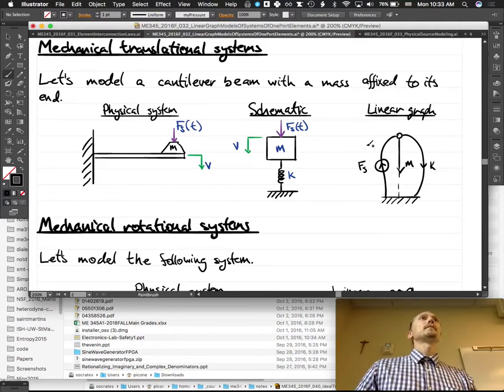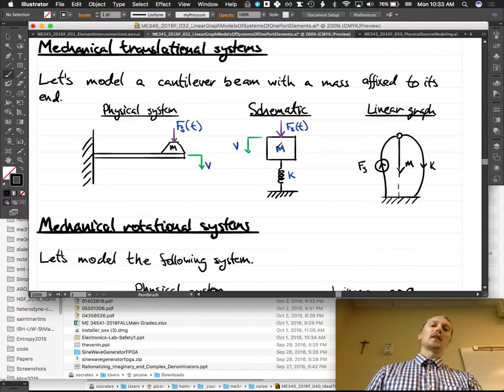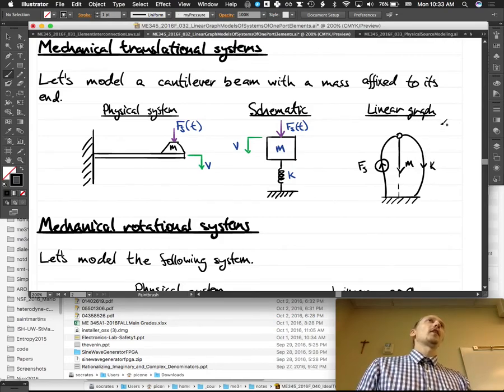Yeah. So we do this so that we have to make sure that this is consistent with our actual physical system model. The sign conventions on the other elements, if you get those wrong, it's not that big a deal. Your interpretation might be wrong, like, oh, this is in tension, there's actually compression. That's kind of a bad mistake, but it's not the end of the world.